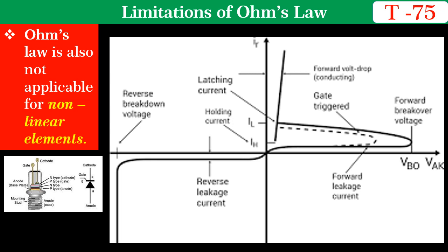First, let us consider the characteristics of thyristor. You see that the thyristor characteristics is nonlinear in this region of the characteristics and hence the Ohm's law cannot be applied in these regions.